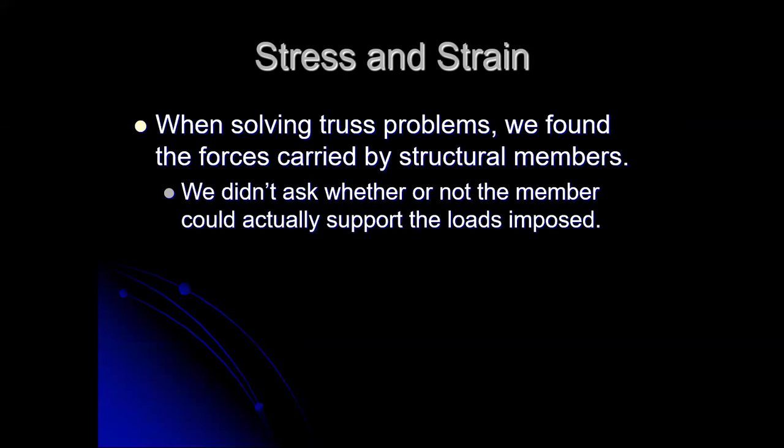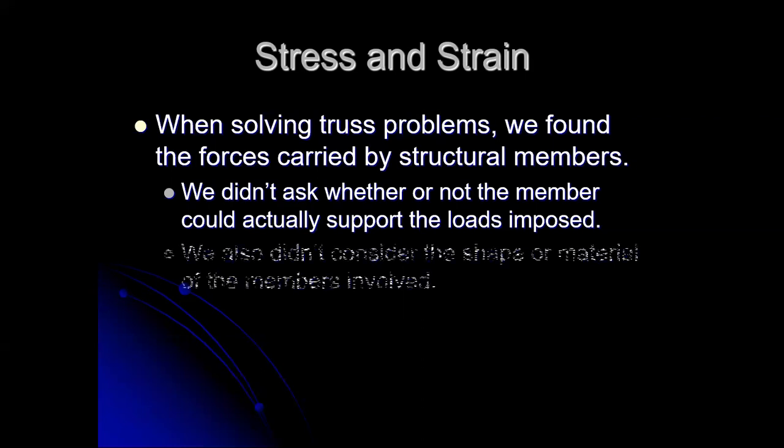We just did the calculation, said, okay, this member carries 2,300 kips in tension. Well, 2,300 kips is 2.3 million pounds. That's a lot of force, and we have to be concerned about whether the material is actually going to be able to handle that load. That's what the strength of materials will buy us, the ability to design and figure out what materials we need and what dimensions we need.